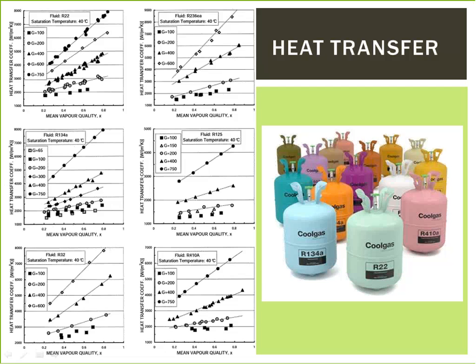The goal is to work with substances that can carry a lot of energy, with high specific heats, and can transfer the energy easily, high thermal conductivity. It is also desirable to have low viscosity to enhance turbulence and reduce the work required to move the fluid.